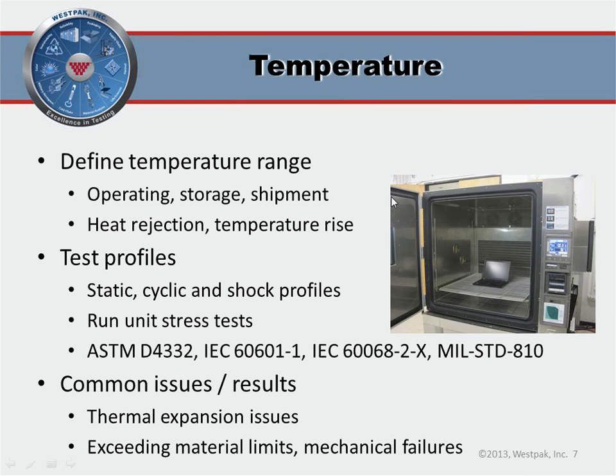One top tip when you do this testing at a contract lab: usually you're renting a chamber for some period of time, so fill the chamber. Put 2 samples in. If you have other projects you want to piggyback, get the most out of it.